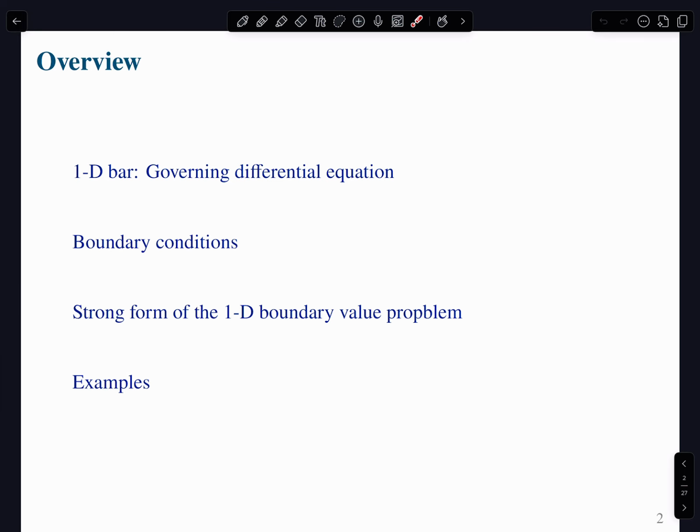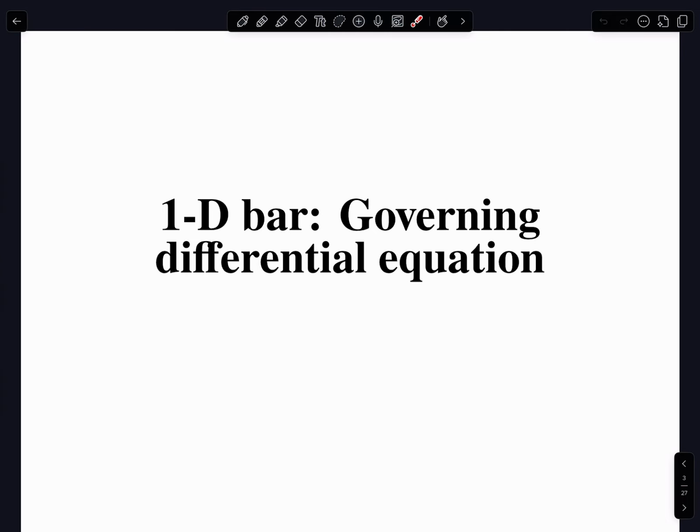And you can use that quantity to see how well you are doing, how far or how close you are from that exact value of your strain energy, because of course, the finite element solution can give you a strain energy. But as I said, if you don't have an analytical solution, you can still approximate the exact value of the strain energy by doing a series of finite element analyses of reduced mesh size, okay? And we're going to look at that also in other lectures. Okay, so let's get started.